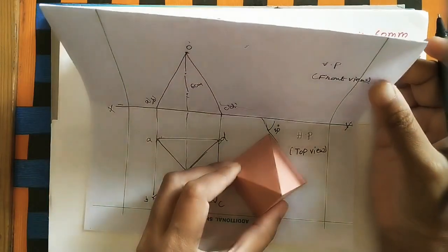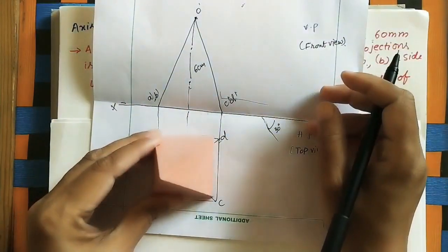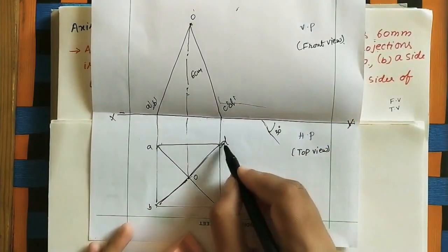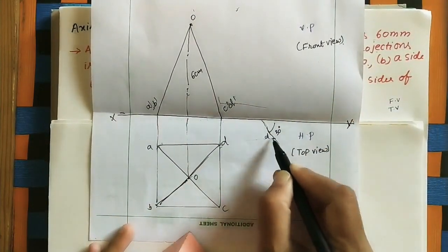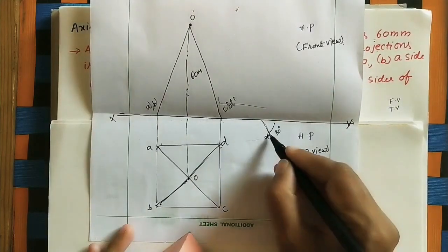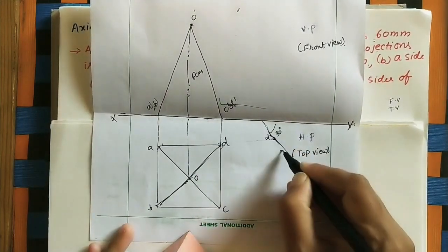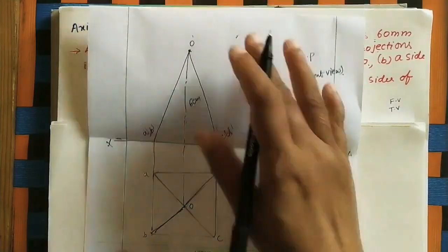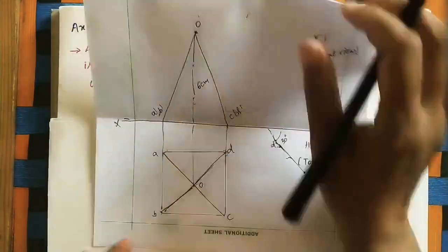Okay, now whatever square is there, we have to take one of the sides on the 30 degrees line. Mark this D point at the same distance here. Take this DC length on this inclined line. Okay, so mark C here. Just do this square. Each side is how much? 4 centimeters.